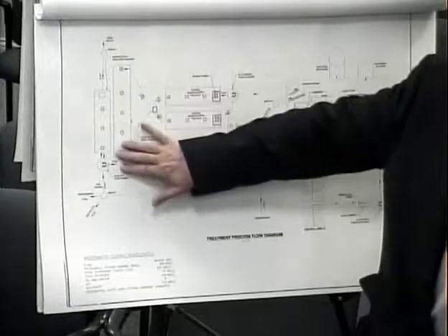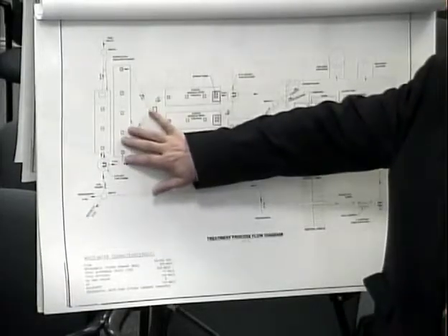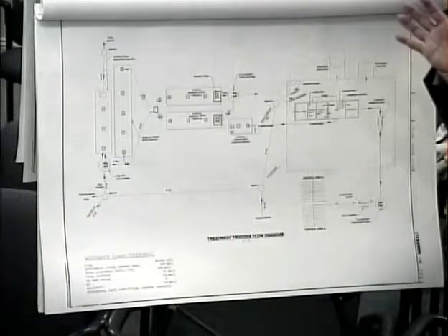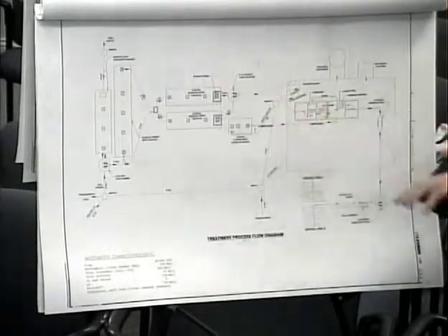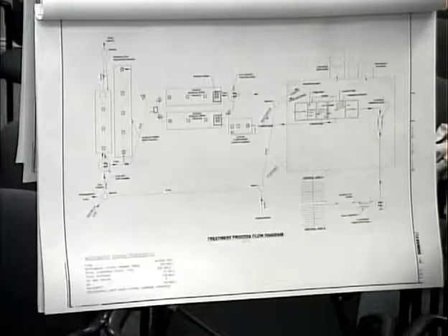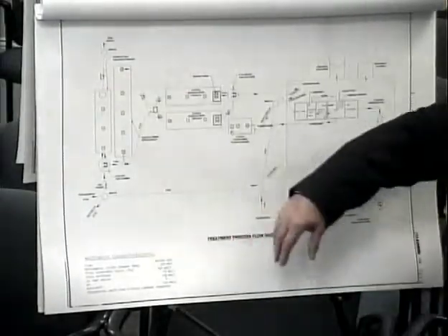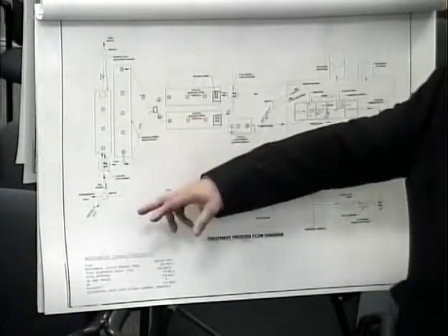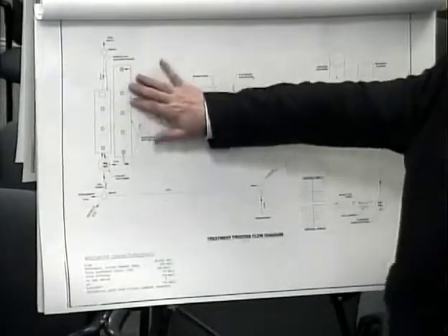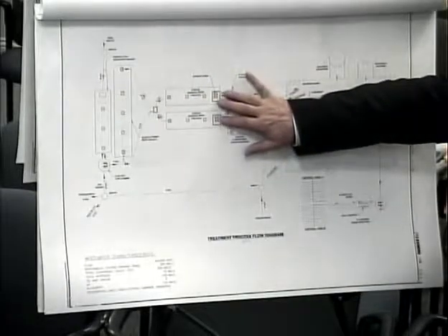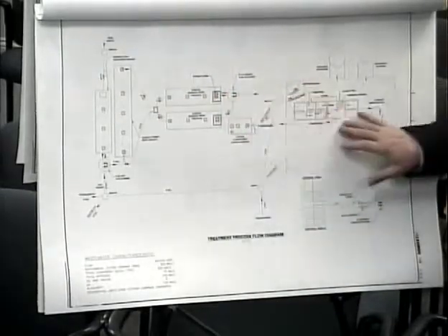We then put in a settling tank. Now the settling tank would still be needed even if you were using one of the STEP or STEG systems with septic tanks, because there are always solids that recoalesce within the system, and you want to settle those out and get those out of the system. And there's also grease that passes through the system as well. By the time it gets here, the water has cooled off a little, that grease starts to fall out, and you want to separate that from the process. You want to get it out of the tank. In this case, because this was raw wastewater going in here, we had a primary septic tank, and then we had two secondary septic tanks or settling tanks, and then we pumped it into the treatment process.